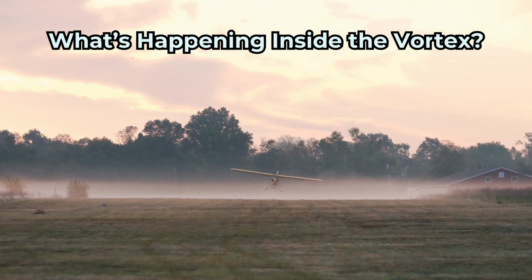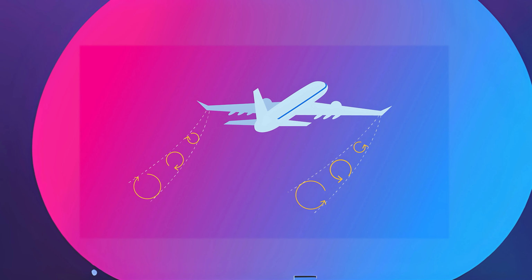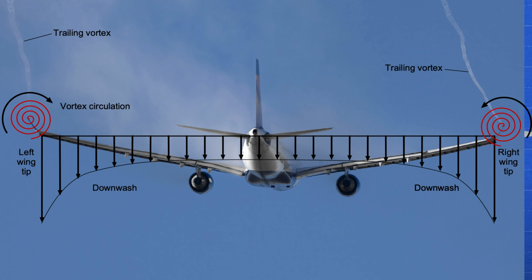What's happening inside the vortex? As seen from the aircraft's tail, the vortex rotates in the anti-clockwise direction on the right wingtip and the clockwise direction on the left wingtip. The rush of air travels downward from the underside of the wing as it rotates around the tip. This downward movement of air is called downwash. It's the strongest right at the wingtip and decreases in intensity as you move along the span to the wing root. The downwash deflects the airflow behind the wing, pushing it downwards.